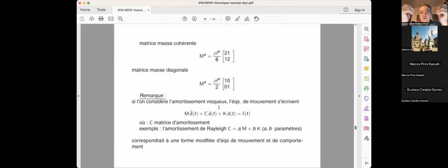So you could always balance between explicit and implicit schemes with the fact that you have more operations per step, but you have many more steps. So as a rough estimate, explicit schemes, if you want to use them, should really be used for very short duration computations, something like explosions, impacts, and stuff like that. Whereas implicit schemes, if you can afford them, you better use in any other type of situation.